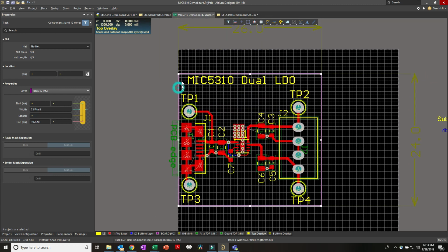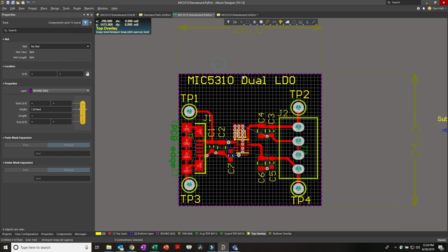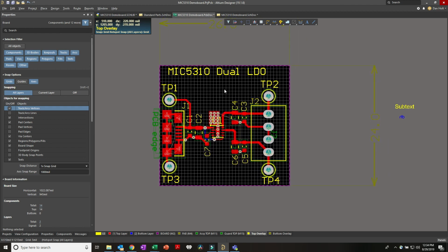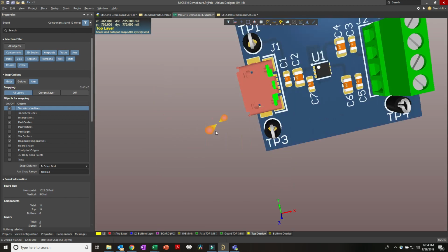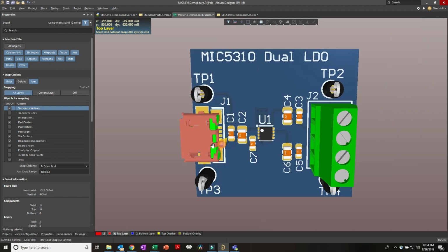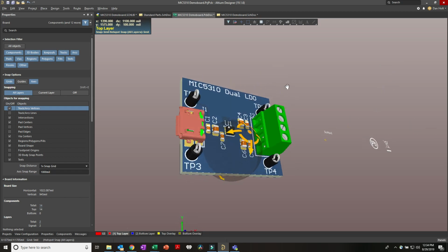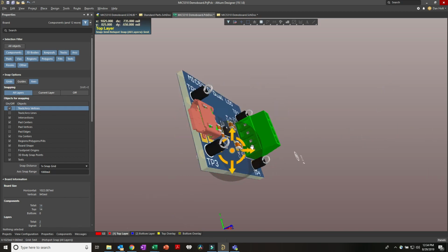Okay. Now they have that placed. Can come here and shrink that up as well. Okay, so pressing 3 again. Well, I can't see anything. Okay, let me show you this. To change the size or the shape of a board, we just shift click and highlight whatever it is that we're creating the edge with, and it needs to be a closed surface. Once we have a closed surface, we're going to say design, board shape, define from selected objects.